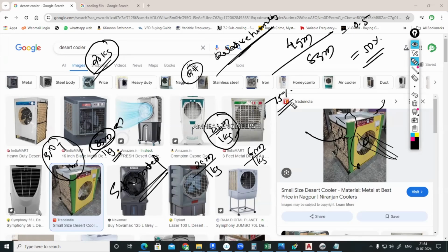Only 25% of space is remaining. 100% relative humidity means the atmosphere is saturated. It already has 100% of water molecules in it. It can't hold any more water. This term is very important. Understood the concept of relative humidity? Relative humidity is the ratio between the present humidity and the maximum carrying capacity. Correct. This term is important.